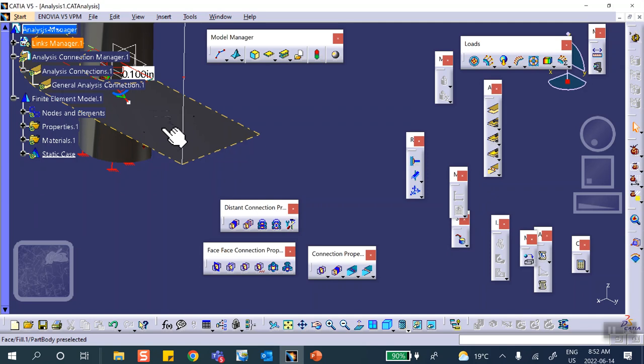Okay, but don't make this with that rigid. Okay, if you're doing it rigid, it must be these 2 points. The reason is that if you make this connection with that, make it rigid, neither one of these will actually change shape. Neither the line will stretch, nor the sheet will stretch. Rigid means rigid.